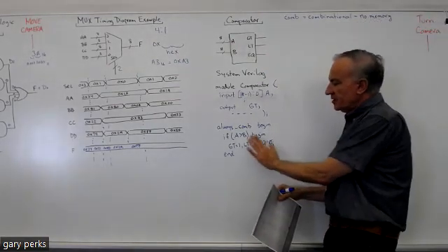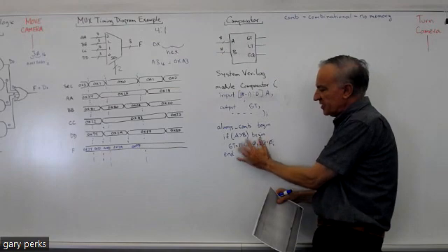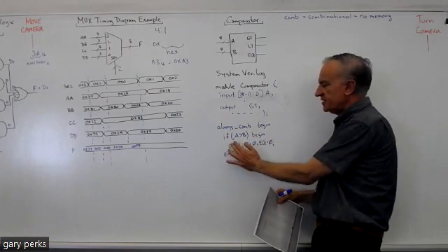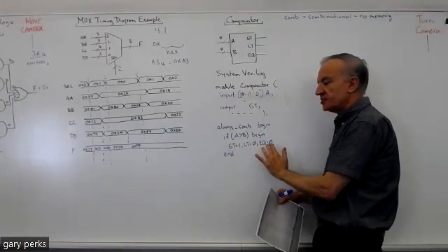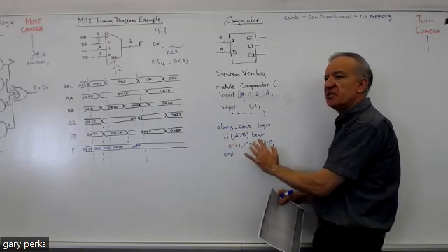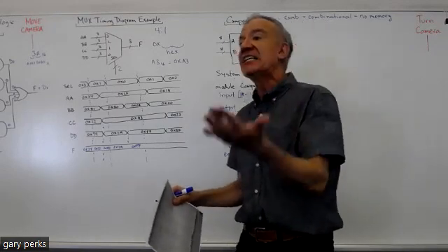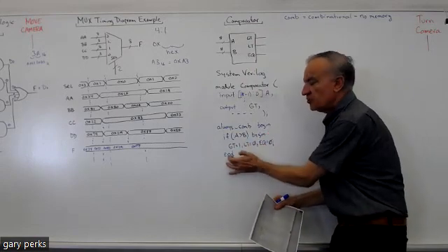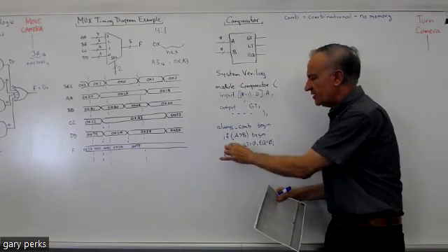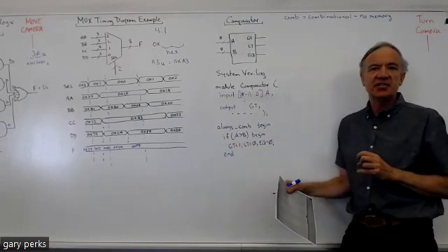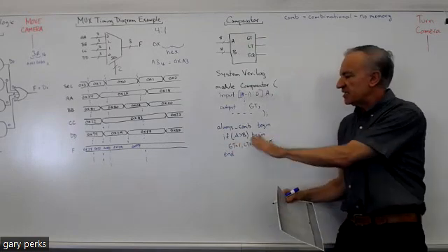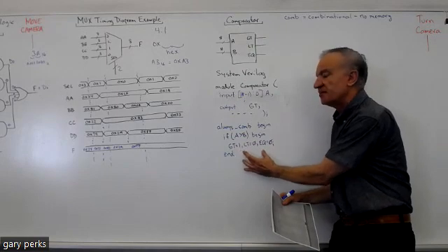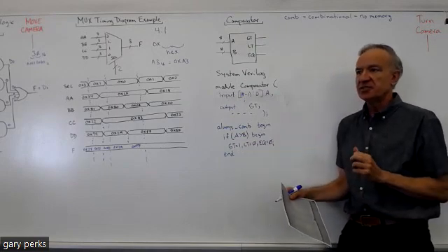So you see this part of the if statement where you see the begin and end here, that's necessary when you have multiple outputs. We have multiple outputs here. If we just had a single output, you don't need this begin, you don't need this end. You could just put if and then just write what that single output is. You only need the begin and end for the if part if there are multiple outputs.